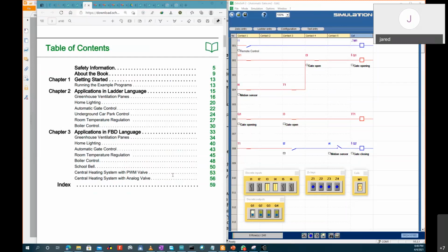We'll do that one as advanced programming for the advanced or basic controls. But you don't need a power supply included because it's for basic automation. They don't want to complicate lives too hard because you don't want to scare people. For small automations, just wire the logic direct, get your power supply from some source. But of course, for complex, that's for advanced PLC. That's why you see they have to pick a power module they put there, because you're going to do that in a rack.